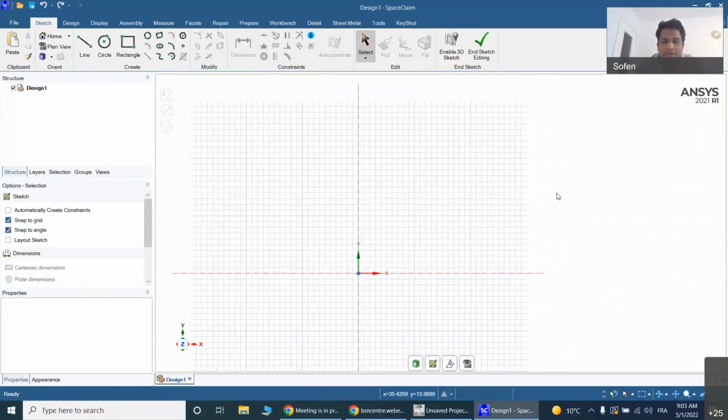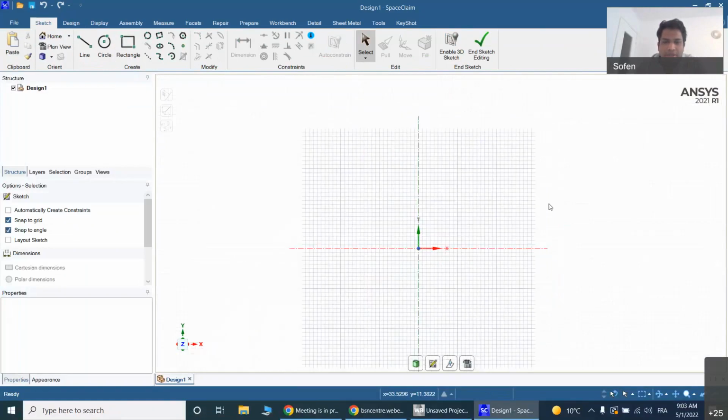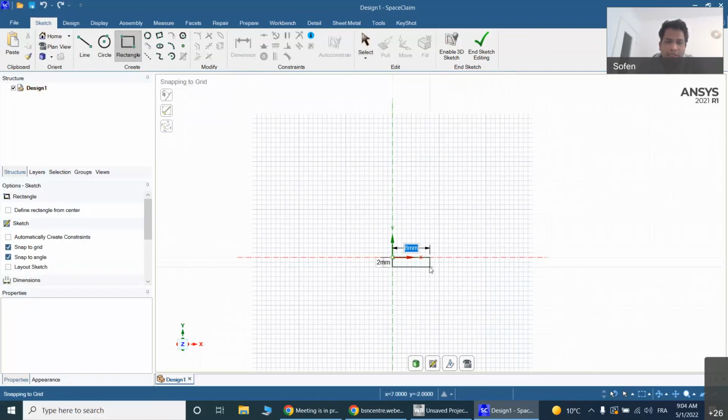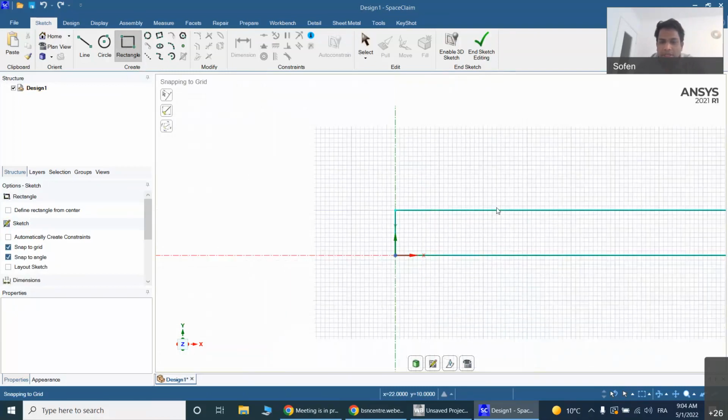Then we want to draw a sketch. Okay. Then from the sketch, we can generate a 3D geometry, rename it, and take it to the solver, or sorry, mesher, to meshing. Then we take the solver and do setup. To do the thing, let's plot a rectangle. Okay, we have a cuboid, so let's make it 0.5 meter, 500.